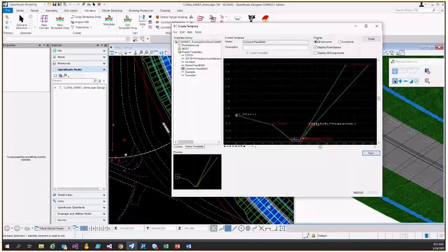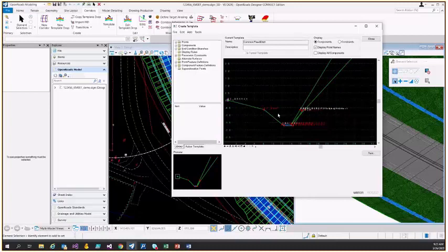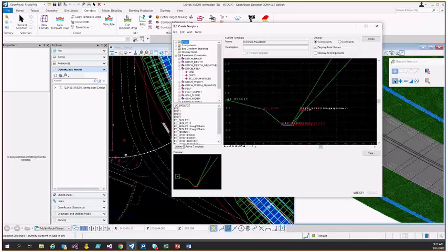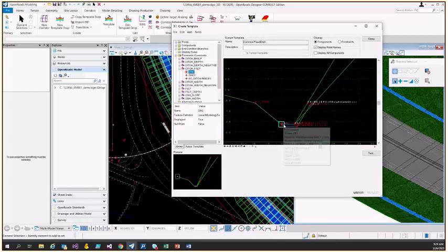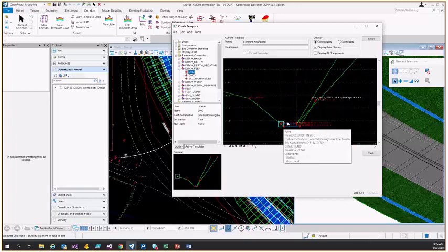So if I come over here and take a look at those parametric constraints, say for example the ditch foreslope, that is actually being set on 3 different points. You can see how, if you need to edit the slopes or the distances, it could start getting pretty complicated. That's what I wanted to try to ease or avoid, so to make it easier, I added all these labels in.